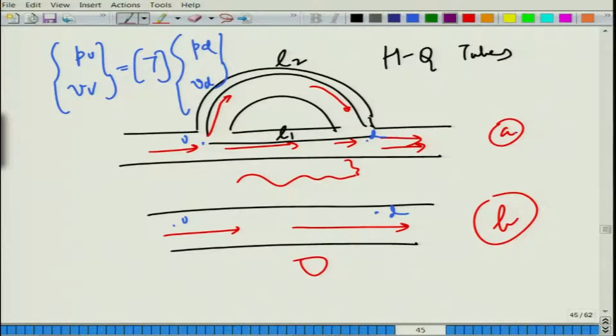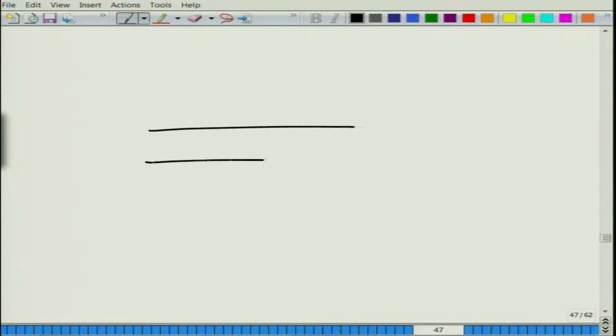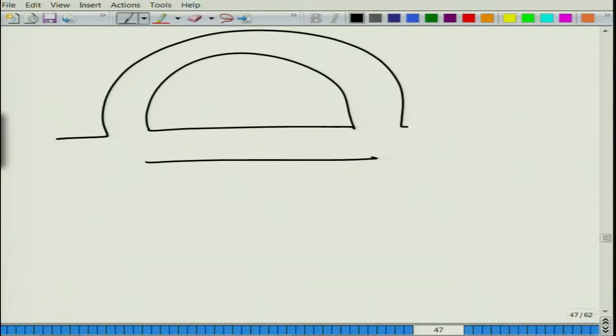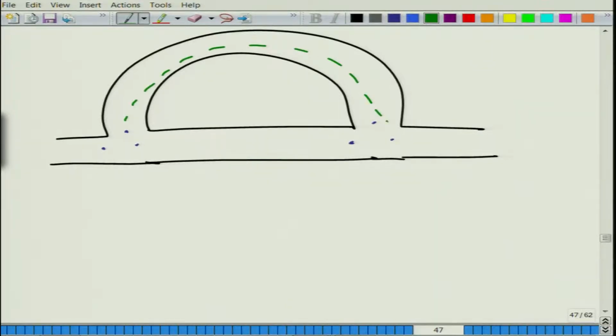And so, let us analyze perhaps the simplest of the multiply connected muffler systems, which is this one. Now, before I begin the analysis of the system shown here, A, I would also like to mention this element, this one, the 2 port element.